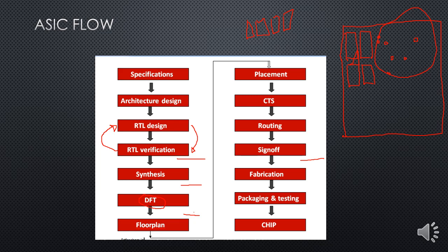For example, say we provide some input over here and we need to get some output over here. In between, we place some memory elements. Let's say we have placed 3 memory elements like this. From the input it goes to the first flop, a D flip-flop, the most common one we use, then to the next D flip-flop, then the third, and from there to my output.